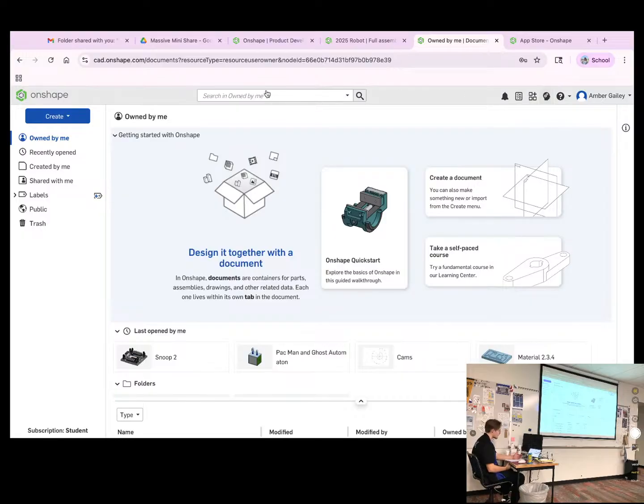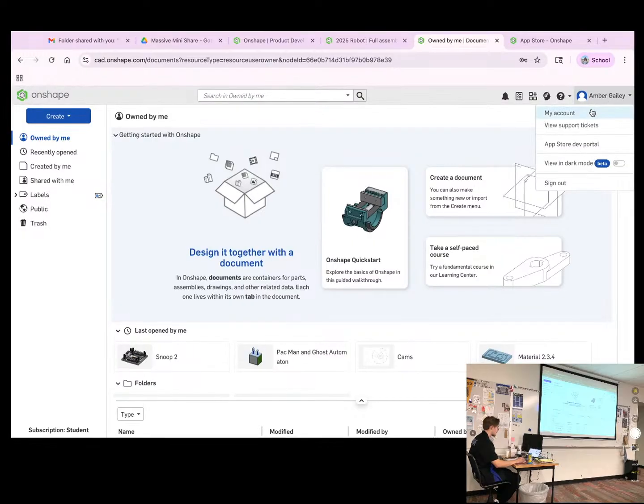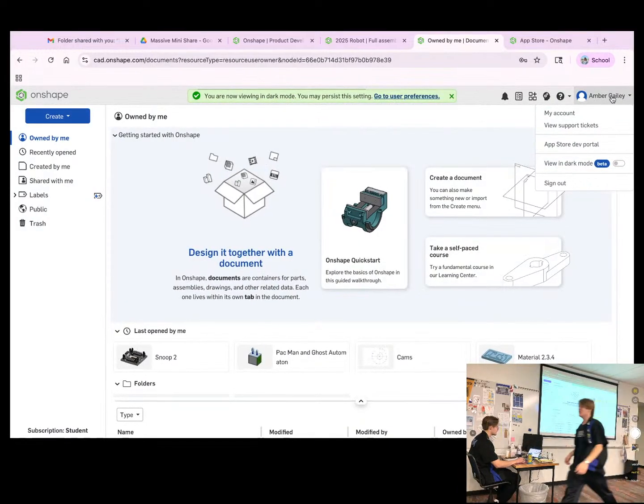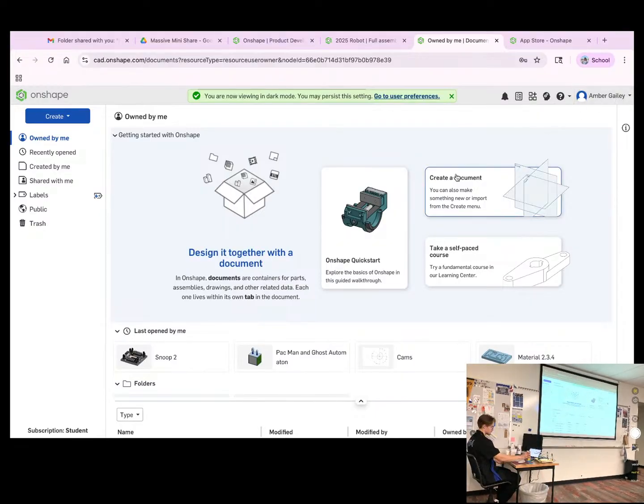Those Clipper tanks, if you guys have ever heard of the manufacturing defect, they had several of them blow up at events. They just became illegal. Then on the right-hand side, we have your account. About 3 years ago at GKC, we actually found a robot that had one of those tanks on it. I immediately took it over to our shop and drilled a hole in it, and we just gave the team a brand new one that we had of ours, and said, look, just keep it, because there's too much danger those tanks might explode.